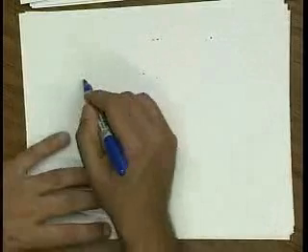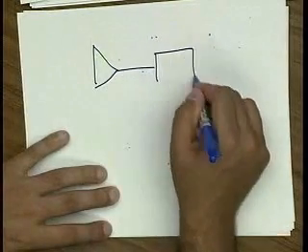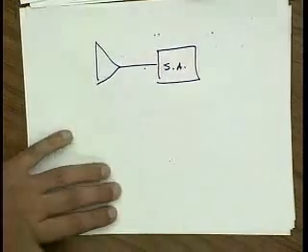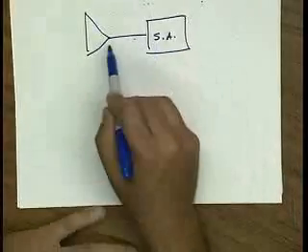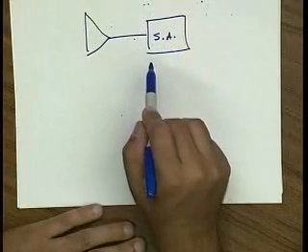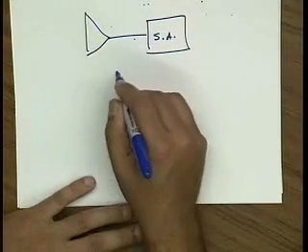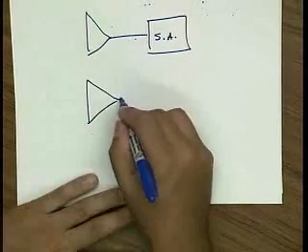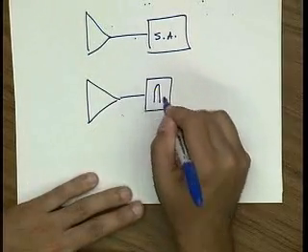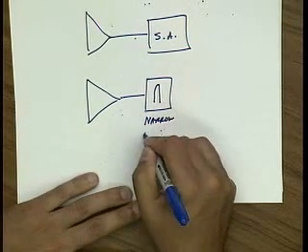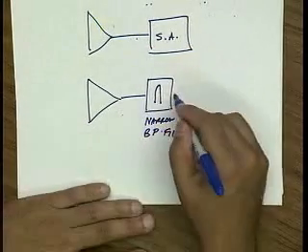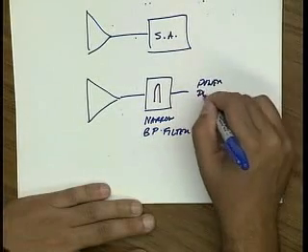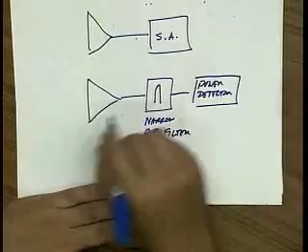In other words, if I take the output of my amplifier and look at it on a spectrum analyzer, okay? A spectrum analyzer, in a very rough way to look at it, is plotting how much power is in a given frequency band, okay? So you can think of a spectrum analyzer as taking the output of the amplifier, applying a very narrow bandpass filter, let's say with sub-hertz kind of resolution, and then going into a power detector and then plotting the results.